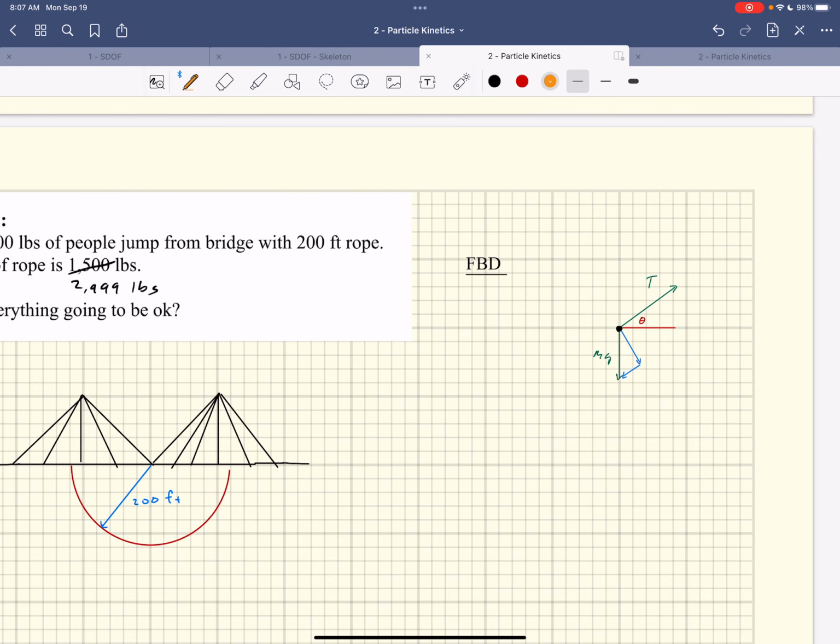Right, which is normal tangent. What do we do for normal tangent? Tangent is in the direction of increasing velocity, right? It's in the direction of the velocity, so that's tangent. Tangent's going to be going down there. Which way is normal going? Right back towards the middle. That's the way that we define it. One is tangent to the path, and one is normal to the path.